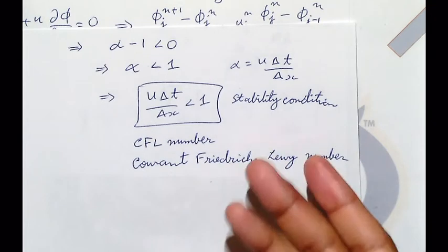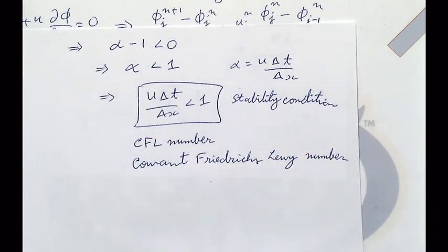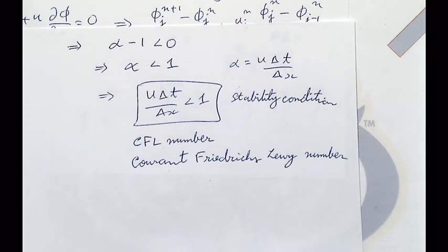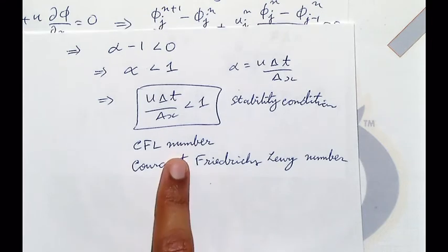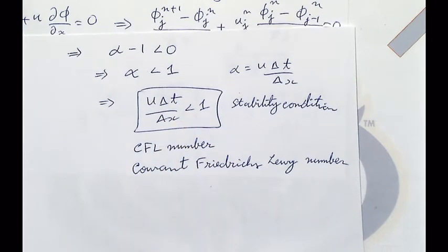Again, it can get very restrictive if your delta t is very small. How do you circumvent that issue, if you're suffering from very small delta t values? You can make delta x larger, right? That will help you with delta t, but that sort of says, okay, I will make my grid coarser and I will get a worse result in space in order to be stable. So it's a possible fix, but then it affects your accuracy.